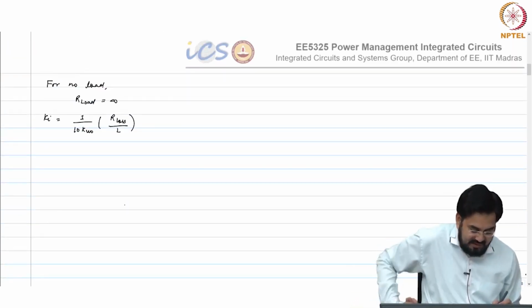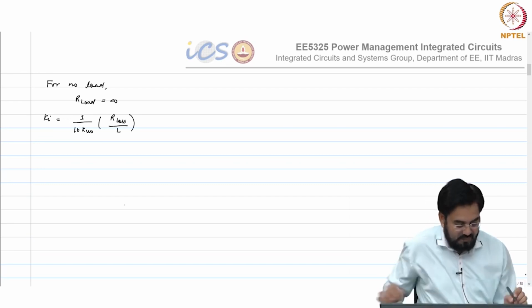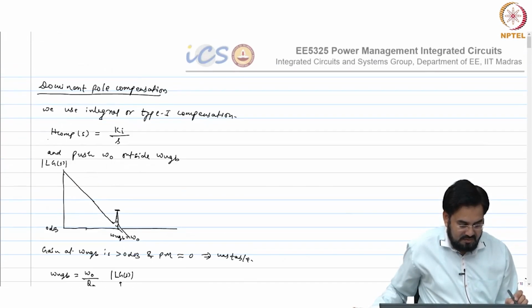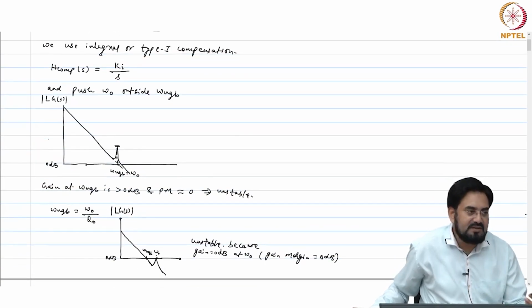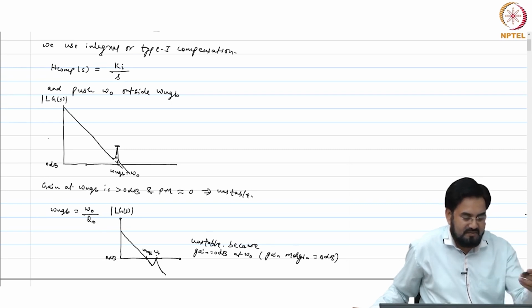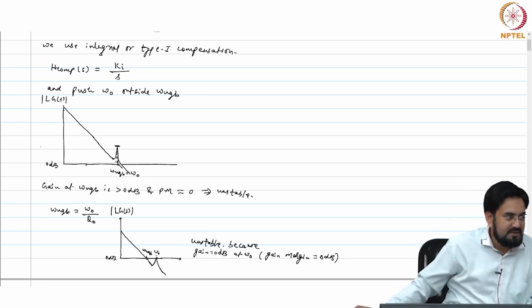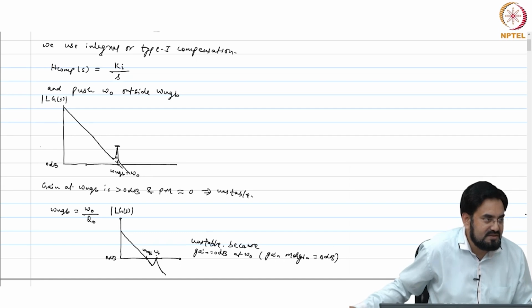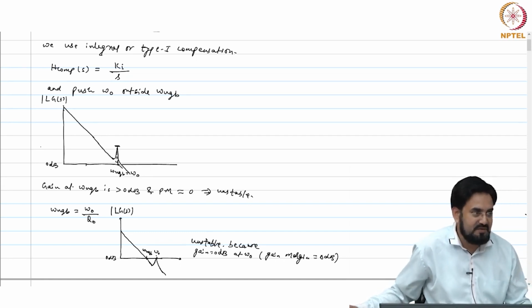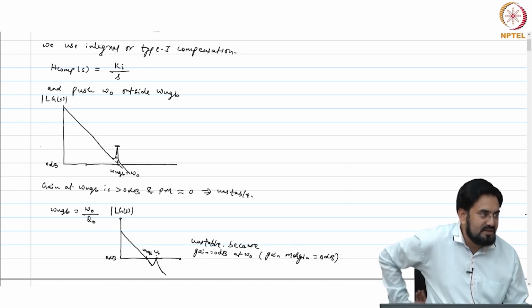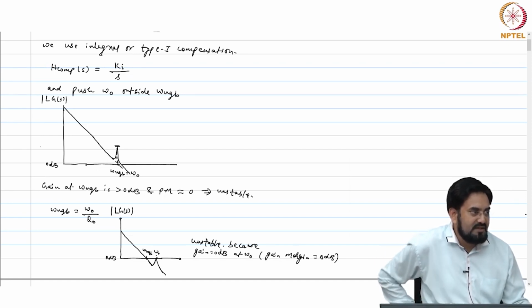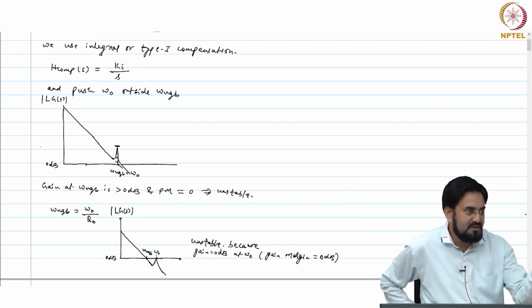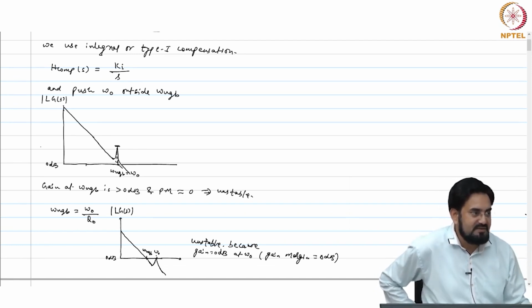So, let's take an example. By the way, why are we doing all this? I mean, why do we need to model basically each and every module? So, small signal is valid for continuous time signal, and this is a sampled system. If you look at switching system, just like you do your switch capacitor circuits, you have to model your switch capacitor resistor and replace it with the continuous time, and that is how you follow.